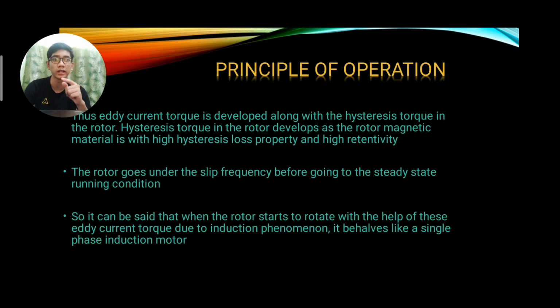So the rotor goes under the slip frequency before going to the steady state running condition. So it can be said that when the rotor starts to rotate with the help of the eddy current due to induction phenomenon, it behaves like a single phase induction motor.